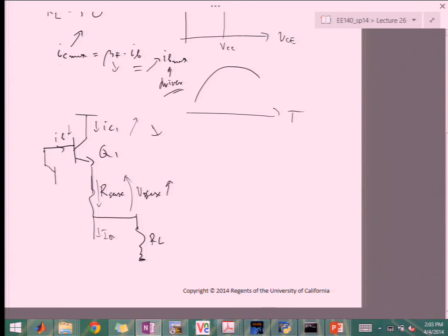So what you do, you put essentially a transistor here in feedback. So now as V sense increases, VBE of this transistor, Q sense, increases. And then I start drawing more current here. So more of the I driver starts going this way and not into the base. Right? And then that's going to be OK, because I'm just going to pump that directly to the output, but it's not going to get amplified by the beta factor of this device. Okay.